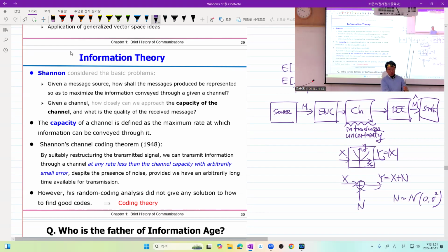Now, the receiver located at Cape Homi receives the signal, and what do you guess? The received signal power is around 100 dB attenuated. What does that mean? The received power is the transmitted power times 10 to the negative 10. It's very, very small. Now, what do we do in the receiver? Of course, we have some pre-select filtering, but we amplify the signal a lot. If we use a low noise amplifier, even though the name says we do not want to add much noise, we can even see the jitters of electrons in our conductors, like the antenna itself. This is a metallic conductor.